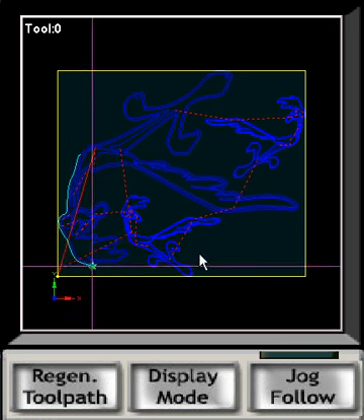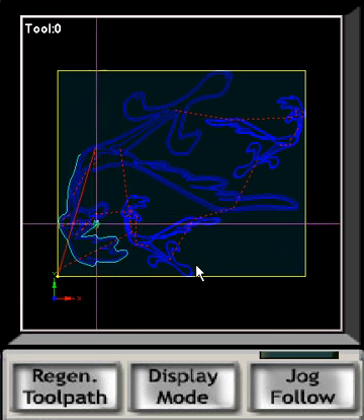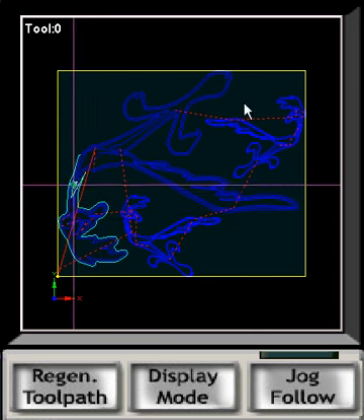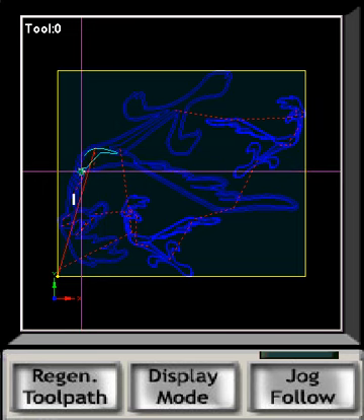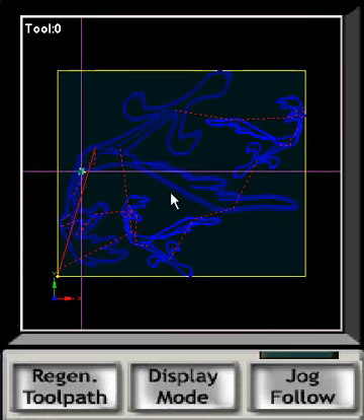Now you do not need to regen this display after zeroing your X, Y, and Z coordinates. However, there is a caveat to all this. This display works very well, and I don't think that you'll have many problems with it. But one of the new rules is you cannot have an A in any of your rotational axes. If you're not using them, you must zero them. To show you an example of why, I'm going to put 45 degrees into my A axis, which you can't see me do, but I just did.